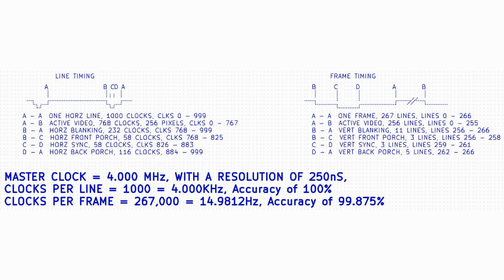Now, there is probably going to be a little bit of corrections where I shift that sync pulse over so that when it falls, instead of falling at the start of a line, at the start of blanking, I will make it fall at the start of the horizontal sync so that they are in time together. I don't show the composite sync here. That means the horizontal sync pulses and the vertical sync pulse together, because at the moment I don't have vertical sync phased correctly with horizontal sync.